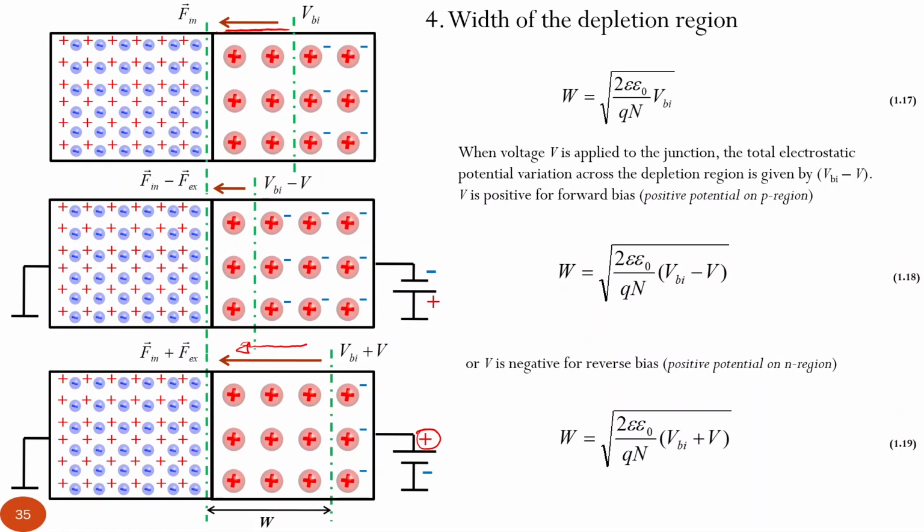It means we will just add up two electric field vectors and get the resultant larger electric field. So when we have so-called reverse bias, which stands for positive potential applied to n-type semiconductor in p-n junction, internal electric field increases.